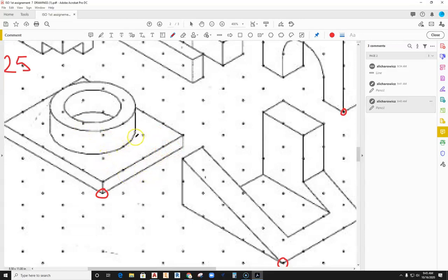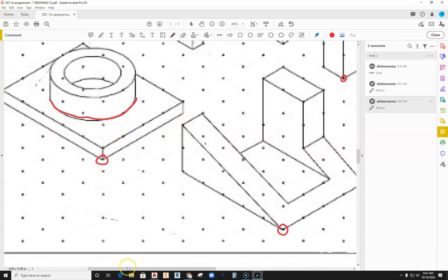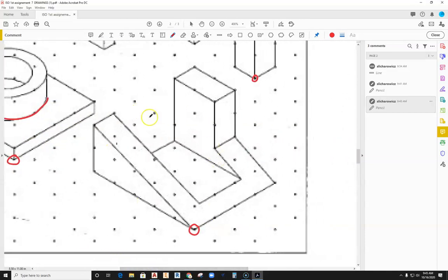Always look for center points off of the object. This arc at this point here is an isocircle, and that's coming off of what would be the center point for this bottom arc down here. So this bottom arc is an isocircle that has been trimmed. You have to look to see, well, where's center on this part? So we probably need to draw some additional geometry and use our center points. This particular object here is also a little challenging.